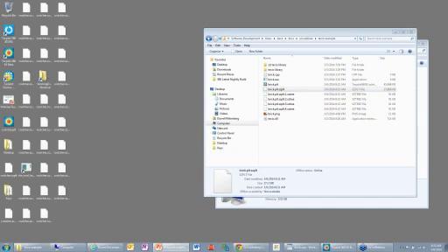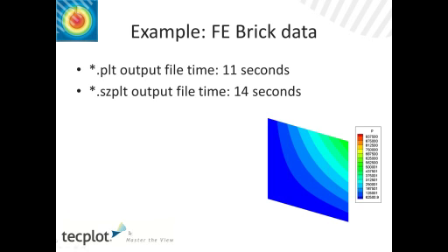There's a question: any issues with big data and 32-bit indexing? Yes, it's the same issue that we've had for a very long time with 360. We're limited to about 2 billion cells right now, per zone. Yes, we have done up to 30 billion cells, but it does require breaking your data down into multiple levels.